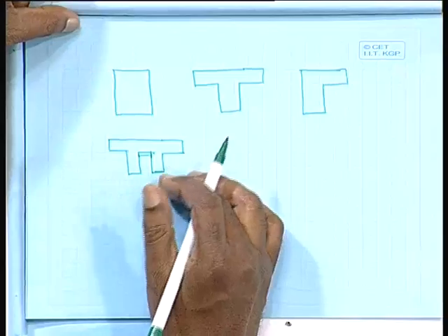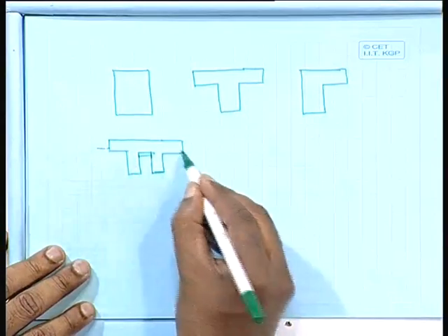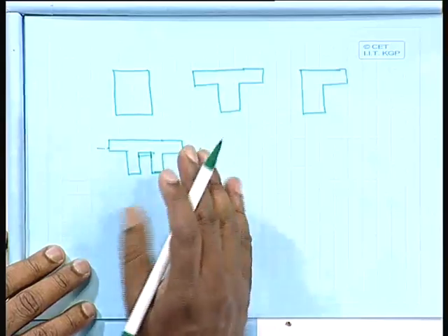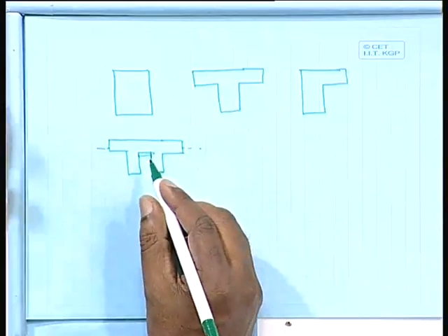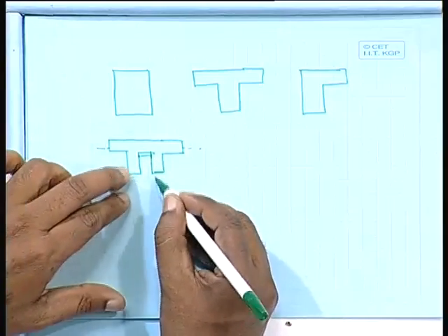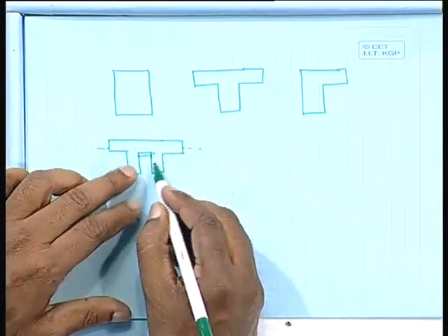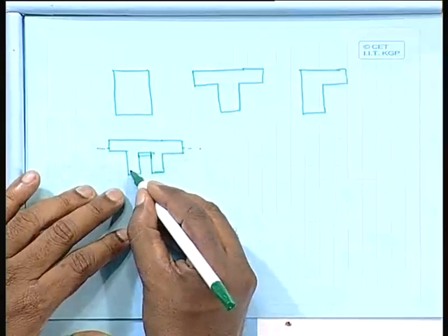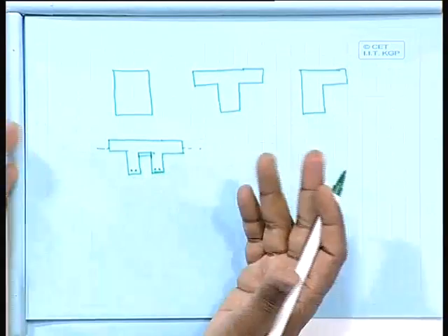Here again it is nothing but the T section, because if the neutral axis can be provided within the flange, then there is no problem, because then it is simply a rectangular section, and the other part of the concrete is not taking any load or moment. Whatever reinforcement you are providing here is the area of steel.